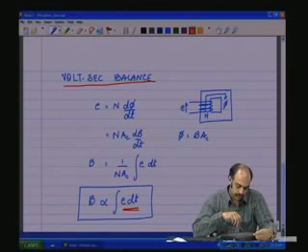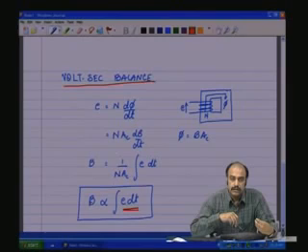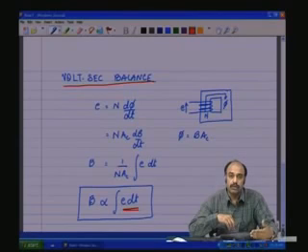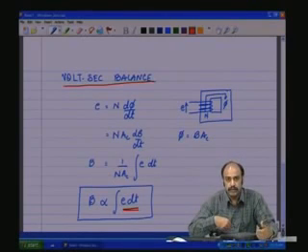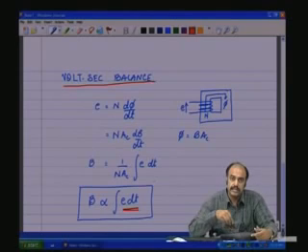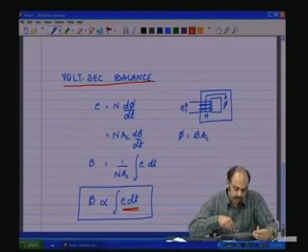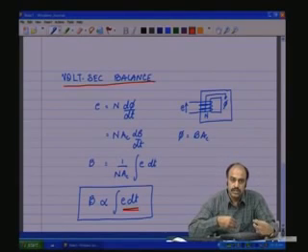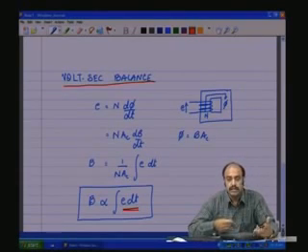for every type of core material, there is a value of flux density beyond which the flux density will not increase. That is when we say the core is saturated and it loses its electromagnetic property. So, if this value, integral of E dt, is continuously increasing, then a time approaches when the value goes beyond the flux density permitted for the core, and the core will saturate, it loses its electromagnetic property, and it will just be a plain short circuit.